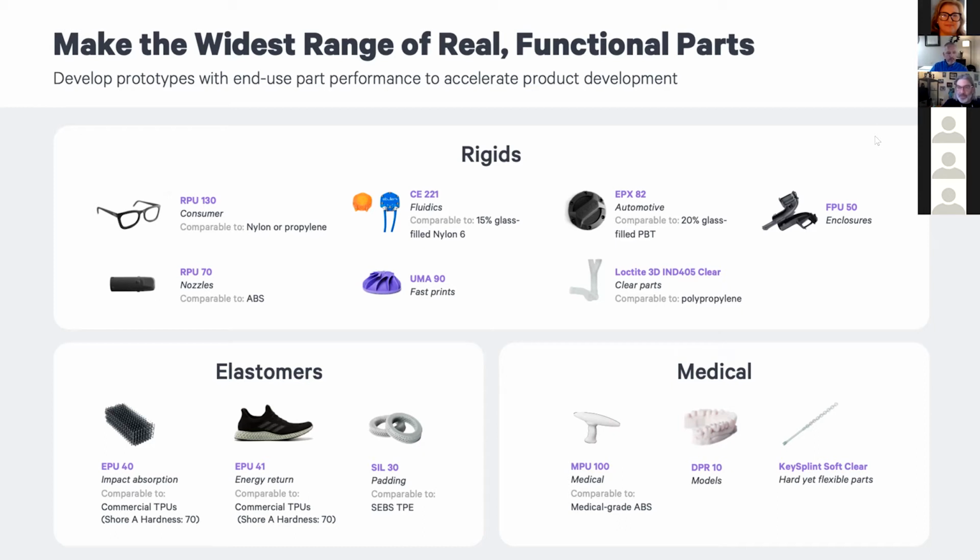Now, the caveat here is that through the power of lattice design, you can variably manipulate the properties of this material and get even new results entered into the design space. So there's a lot of exploration to have there as well. And then we have a silicone type material, Sil 30 it's called. It's not a true silicone, it's a silicone urethane. It's biocompatible. It's great for soft touch buttons. I utilize this material a lot, combining it with other Carbon materials, with rigids.